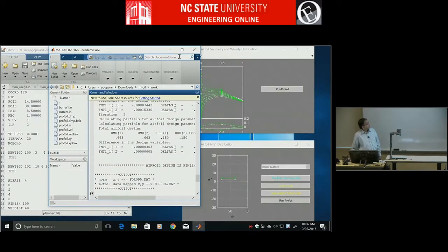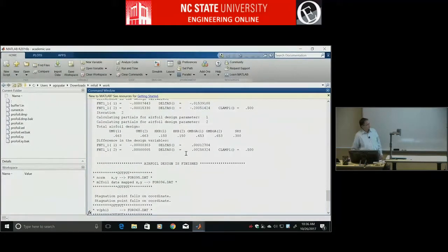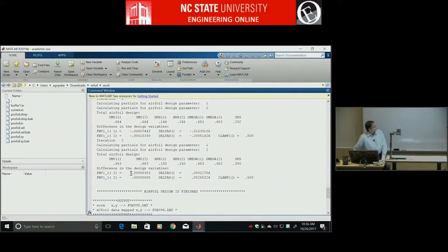And these are the Newton iterations. So we'll talk more about Newton iteration in a few minutes. But basically, these are the residuals, and residuals should be pretty small, like 0.000 something. And these are the steps in the Newton iteration. These should also be pretty small, 0.00 something. Like if this is 1 or 0.5 or something, that means the iteration hasn't converged.